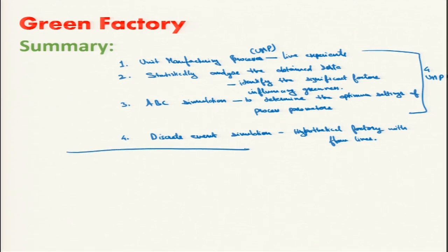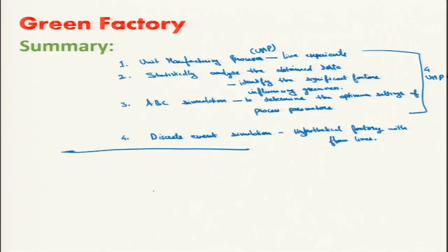Now, this is what we did to develop a green factory. So, this is a kind of a pseudo algorithm or the steps that we took to develop a green factory. Now, what did we get from this green factory? We identified that the vegetable oil is suitable for this manufacturing for certain reasons. Human operator is not affected, his health is not affected by this. Number 2, the machining quality was similar, if not better, it was similar to what we can obtain in flood. So, these were the few observations for that, and also we selected MQL which has lesser consumption of fluid.